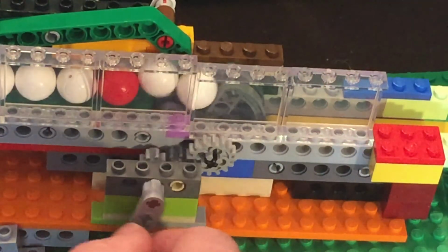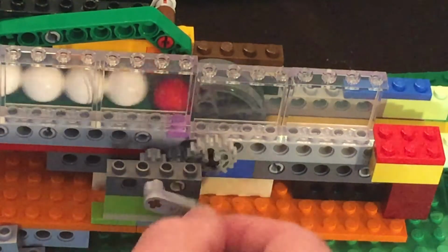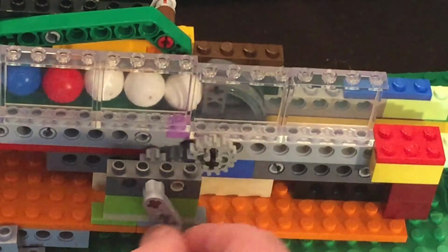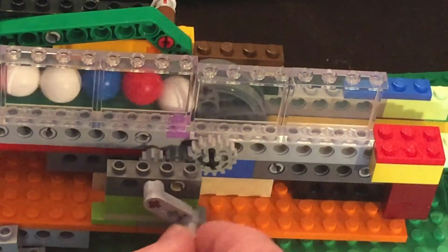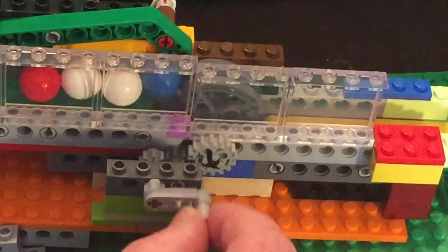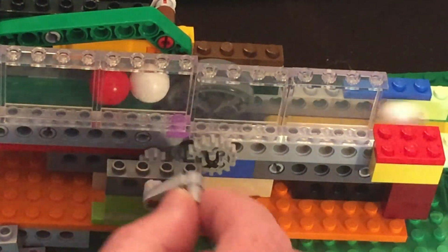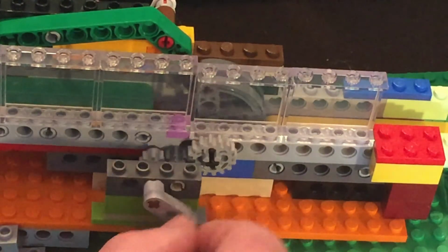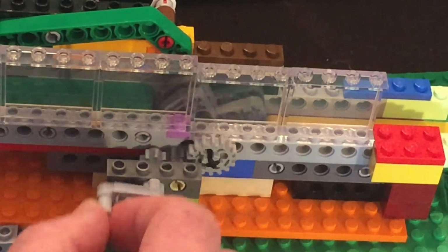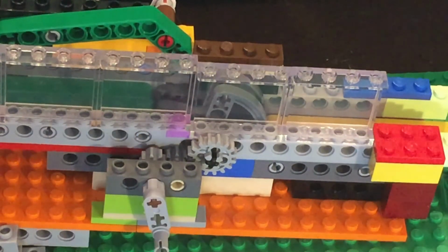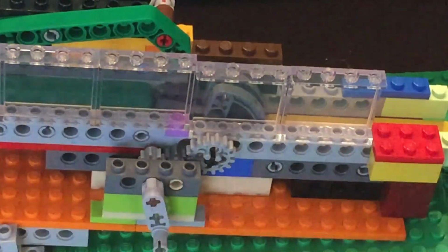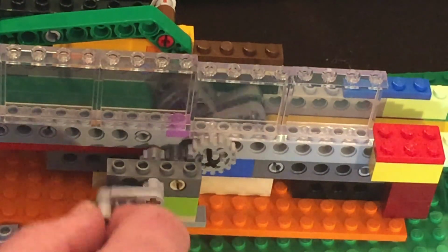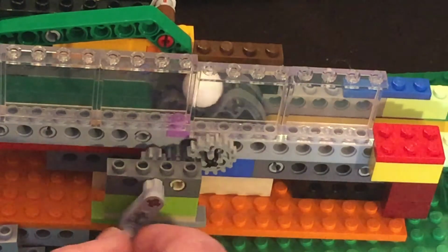Finally, this is my favorite design. It has a vertical wheel with notches in it that will fit exactly one ball at a time. As the wheel rotates, it carries one ball forward in the notch while holding back any other balls. I love the action on this. It's very smooth and it doesn't have any vibration like the reciprocal designs do. And since the wheel is lifting balls up, it won't jam them or suffer from random arrival. Push was a problem with this design, as balls could be lifted up and over the wheel while it was turning and advanced when they weren't supposed to.